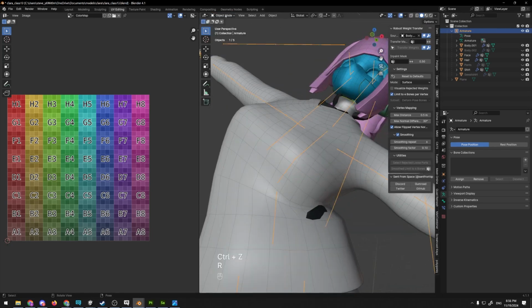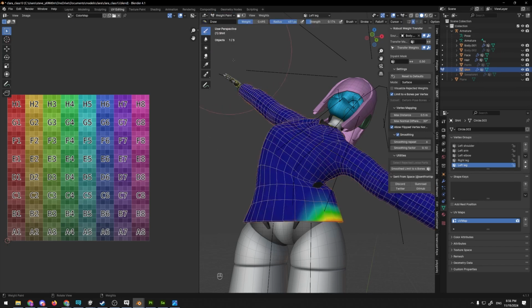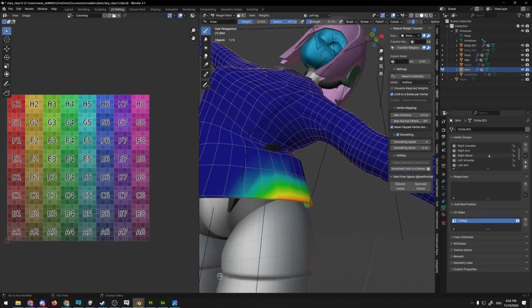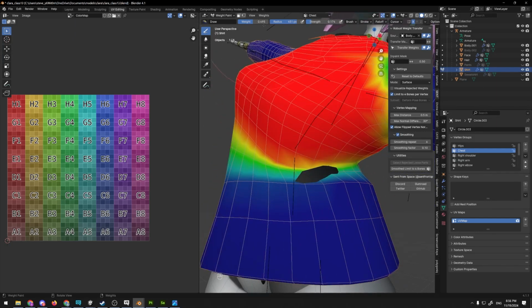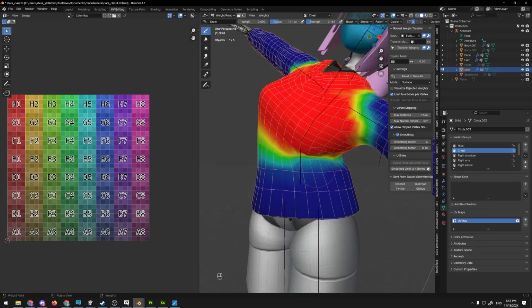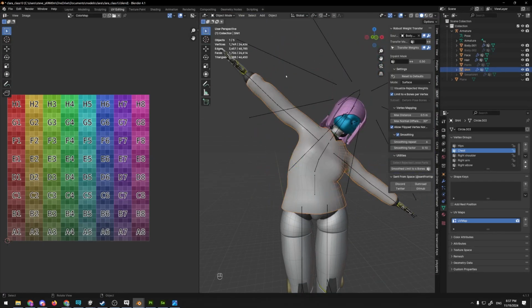And then we could go, this is a little bit weird with symmetrical objects, but you could go into weight paint, go kind of find what's deforming incorrectly. In this case, our chest is applying too heavily down here. And then we could just set our weight to 0, strength relatively low, radius relatively low, and then just kind of paint until it looks better. Still not perfect, but better. Weight painting sometimes manually is beneficial if you run into these sorts of issues.